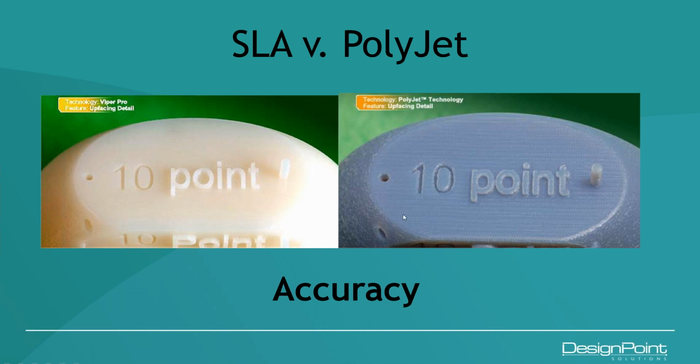And I do want to reinforce that this is literally the same exact model file being printed on 2 different technologies, the SLA technology on the left and the PolyJet on the right, using the high resolution of both printers. And if resolution and clarity is something you're striving for, hands down SLA is the way to go.